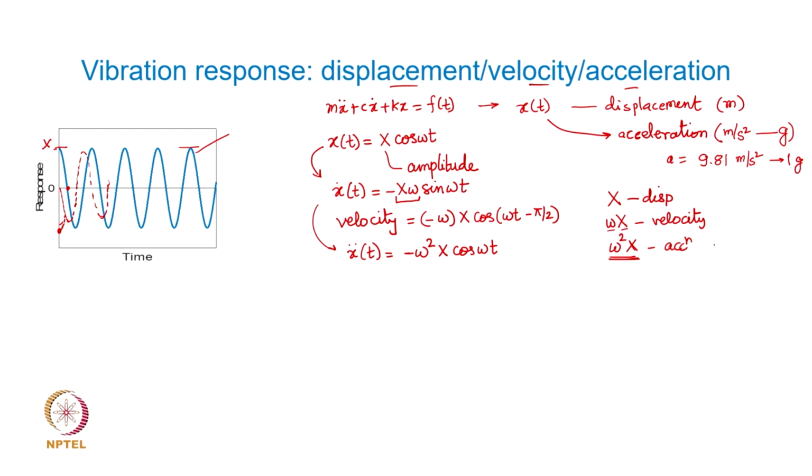Okay. The unit of velocity response is obviously going to be the standard unit, meters per second, but in practice velocity based measurements are typically recorded in millimeter per second. The displacement can have any unit as such, but many times for small levels of vibration micrometer is the displacement unit, because typical mechanical vibrations will not go beyond a millimeter. Okay.